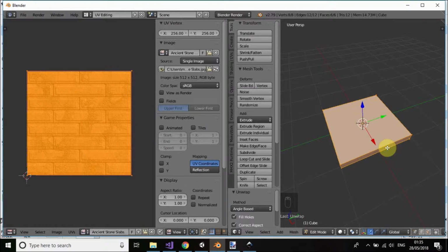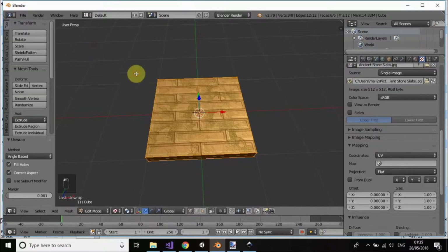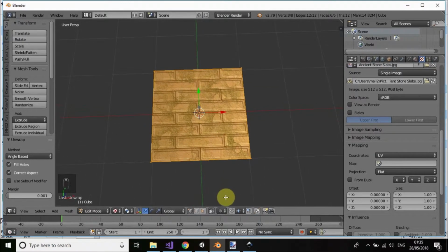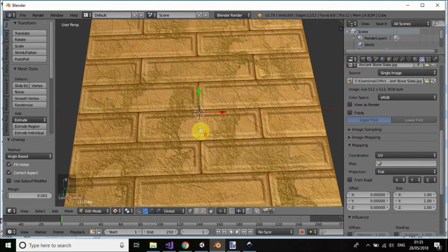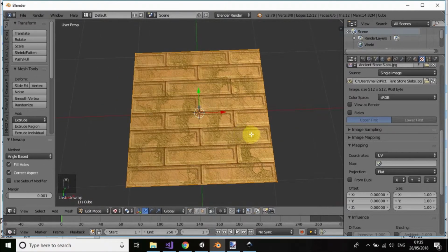If you have a different shape, like some irregular shape, a human face or anything, so if you are doing the texture operation here, you need to adjust your texture with the editing options, or you may need to add more texture and do the job. Okay, so that's not the subject here. So we have what we needed, so let's switch to our default view. So there you go. So that's our slab with some texture applied on it. So I hope it looks like a wall now.